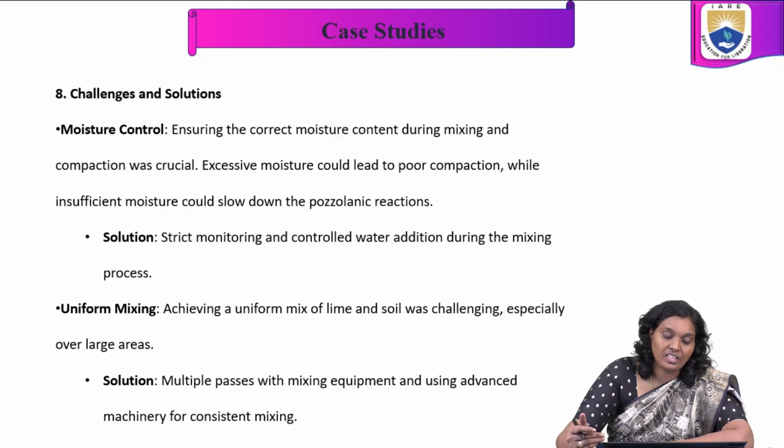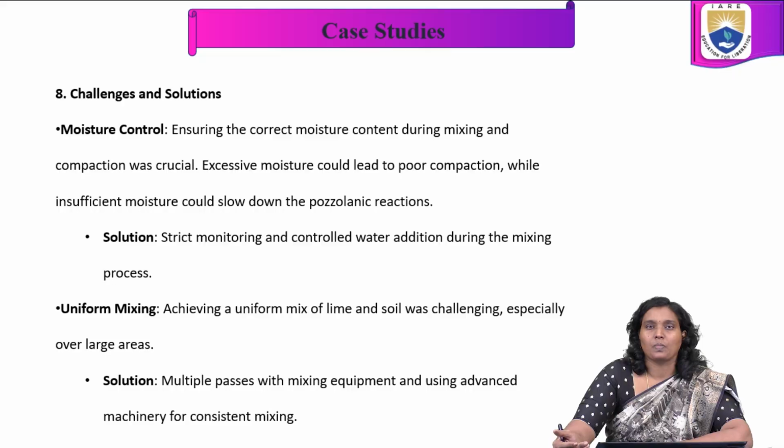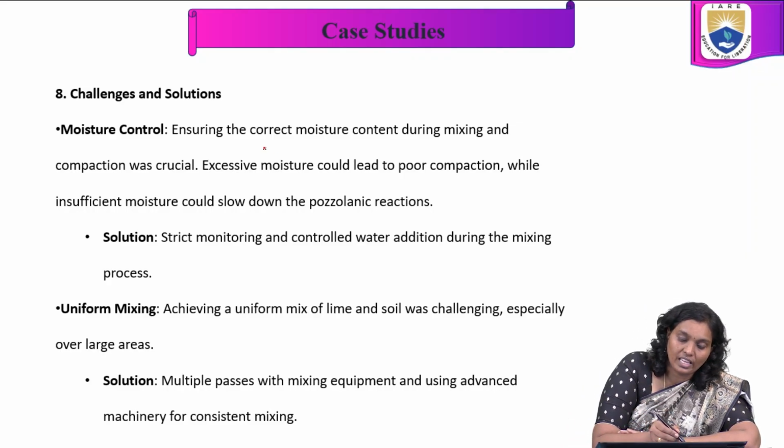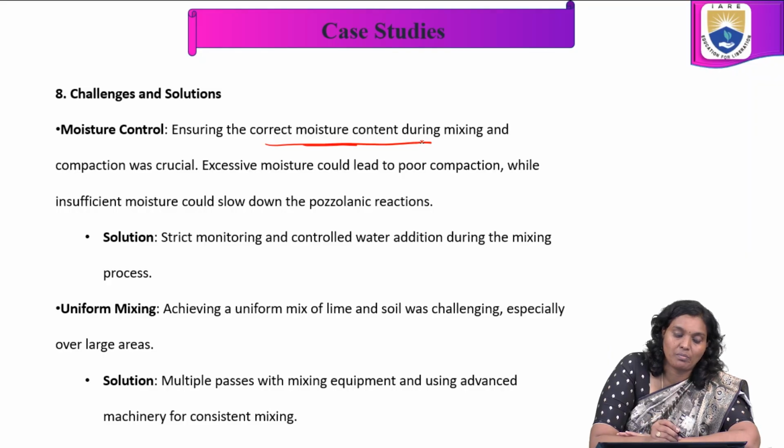So now, ensuring the correct moisture content during the mixing and compaction was crucial. Excessive moisture could lead to poor compaction, while insufficient moisture could slow down the pozzolanic reactions. Here, strict monitoring and controlled water addition during the mixing process. Here, we are ensuring the correct moisture content during the mixing and compaction.